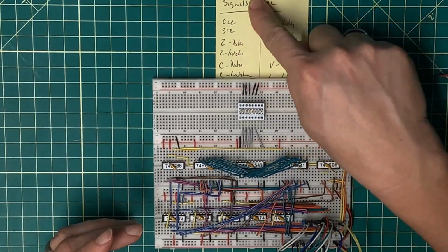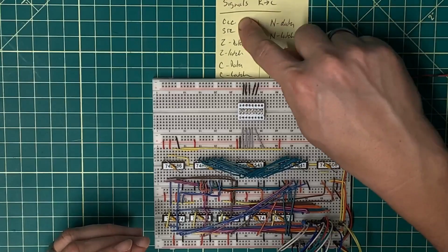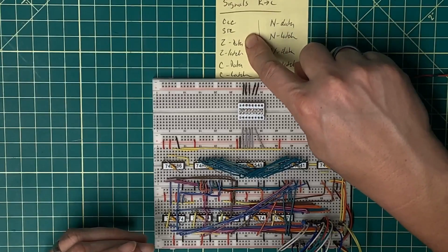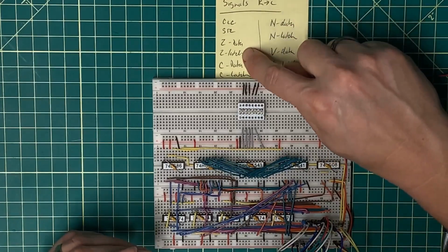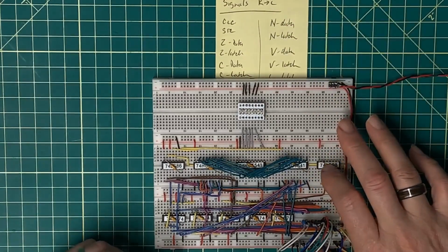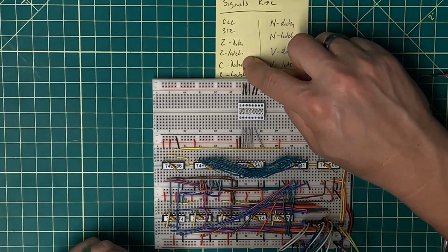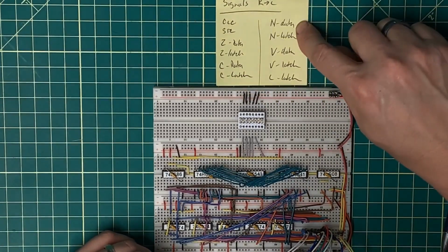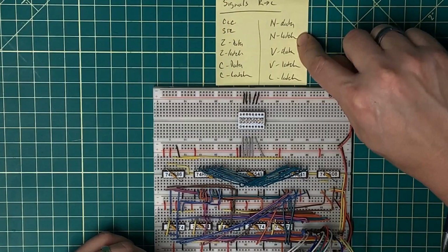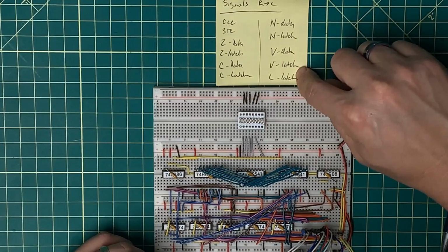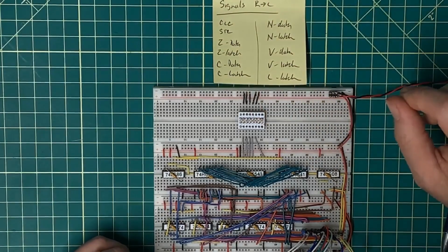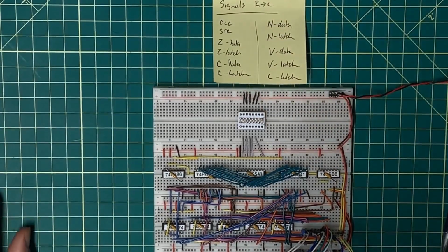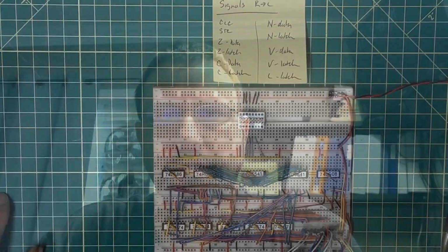So I do have my signals documented. This goes from right to left. So clear carry, set carry. The Z data needs to span both, but the Z latch needs to have separate signals, one for the program and one for the interrupt. Carry data, carry latch. Negative flag data, negative flag latch. Overflow data, overflow latch. And then the less than latch. So I need to hang on to that because that's my crib sheet for my flags register. Okay, that's going to take care of the 2 flags registers.